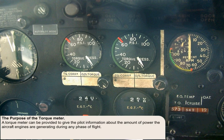A torque meter can be provided to give the pilot information about the amount of power the aircraft engines are generating during any phase of flight. The instrument may be calibrated in units such as pounds per square inch, pounds-feet, Newton meters, brake horsepower, or any other suitable unit of power.